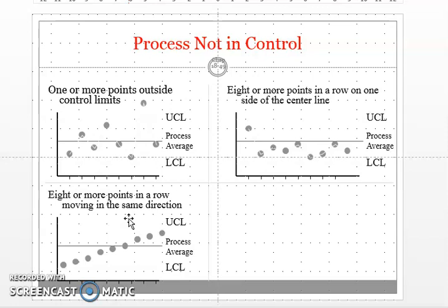This indication of trend is due to tool wear, the wear of threads on clamping device, the effects of temperature and humidity, or the accumulation of dirt and clogging of fixture and holes.